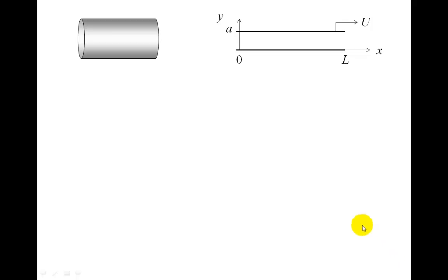On this next slide, I've sketched in a couple of things. One is just a picture of the mass for purposes of free body diagram, and the other thing is the flow that we're analyzing, which is the flow in the gap between the mass and the wall of the tube. So the gap width there is A. Now, just a quick remark, this is a narrow gap compared to the radius, and that allows us to ignore curvature effects. So we treat this as flow between infinite parallel plates with a length extent in the third dimension that's equal to the perimeter around this tube. And so that allows us to avoid some of the complications that would happen if we went with a cylindrical coordinate system, and the price in terms of accuracy is quite small.